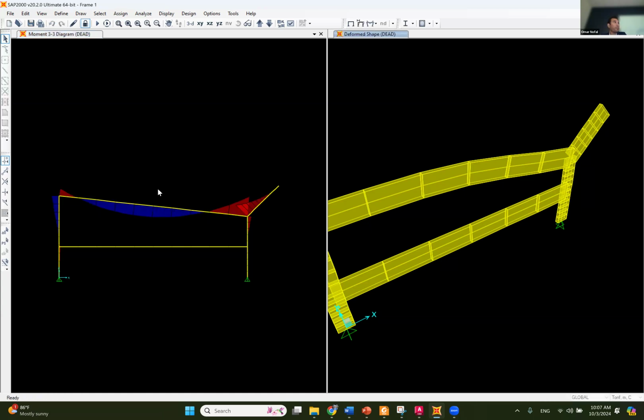You see what happened? Right now, we started to have a parabolic curve and it started to calculate the bending moment at each joint that you have, and the parabola started to show up. So that's actually something that I need to mention, that the finite element method, which this software is using, is an approximate method. It's not the exact solution when you're solving problems. What does it mean by approximate?